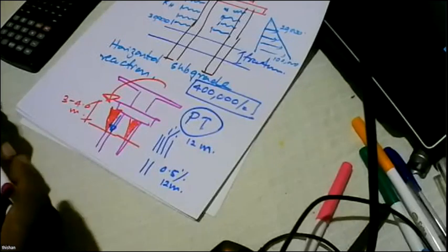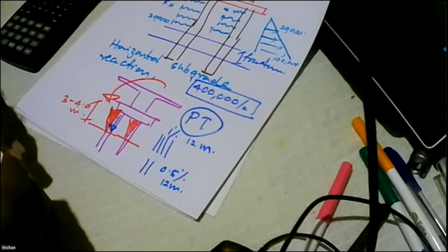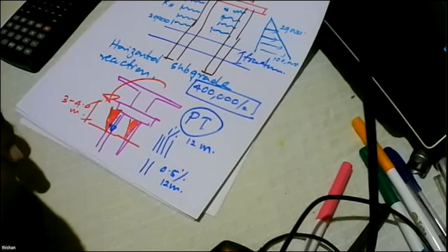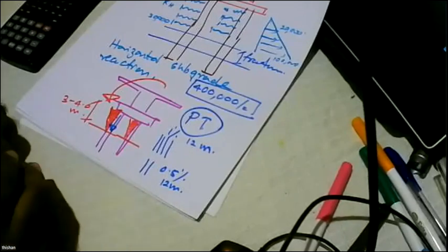A lot of engineers put a lot of reinforcement into the pile, even going into the bedrock. But very capable engineers have designed a lot of pile foundations where they have omitted the reinforcement, showing that the pile is not subjected to any bending moment.